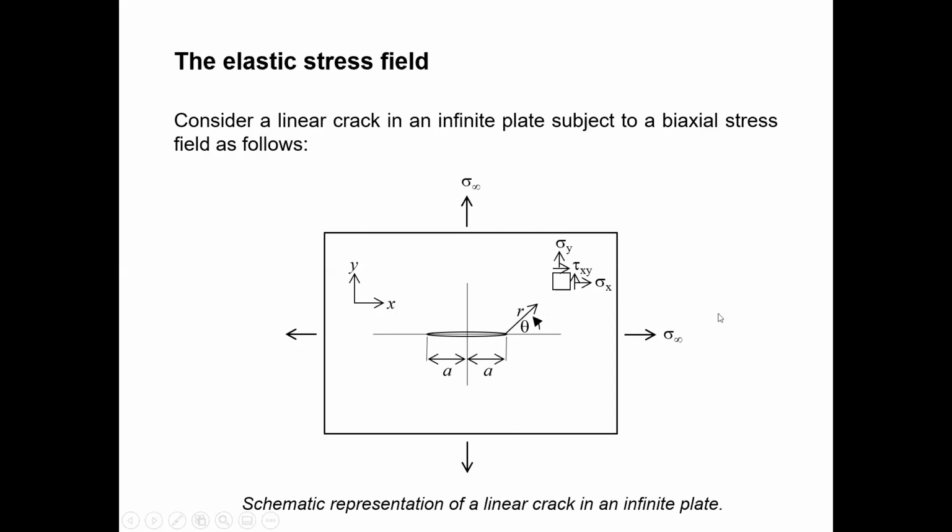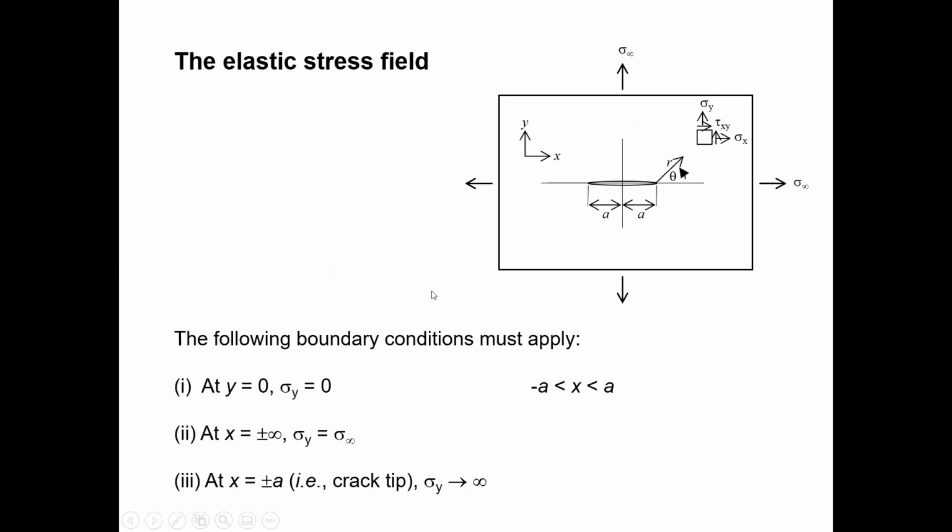Here there are only biaxial stresses, so you know there is no shear stress. But when you calculate the inside points, there can be shear stress, even though the loading is biaxial only. So this is the general term, that's why they mention it here. We will use this kind of model to calculate the Airy function.